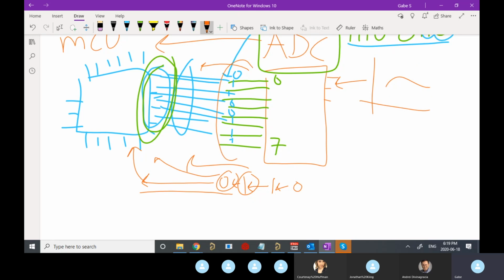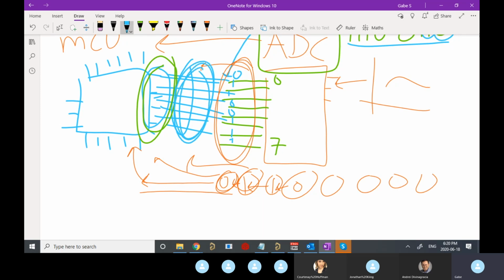And so that's a serialized communication. Instead of all the bits being sent at one time in parallel, like in just one shot, you send 8 bits at a time. Now you're sending 1 at a time, 8 times. You can imagine, right? And now the benefit of this is that we no longer need 8 wires, right? We no longer need 8 pins on the microcontroller. We no longer need an ADC that has 8 pins here. All we need is 1 pin. 1 pin on a microcontroller could read all of the bits from the ADC.